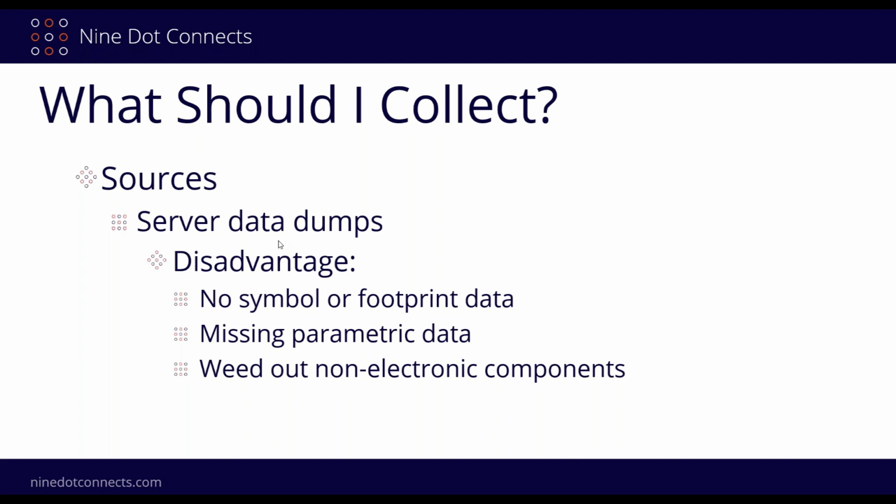libraries, or you can create a viable symbol, like if it was a resistor, okay, fine, you know what that's going to be. If it was 0402, fine, use the 0402 footprint. But you have to find a viable symbol and footprint, either through the libraries or just by the fact that you were going to have many of them that had the same type of symbol and footprint. So those are the 5 criteria. And so we were able to go through that and basically extract out of the 14,000 a little less than 4,000 components for them in order to continue with their library. So that just gives you an idea of what we can do with the server data dumps. In this case, we had to lean on it very heavily to make it work.